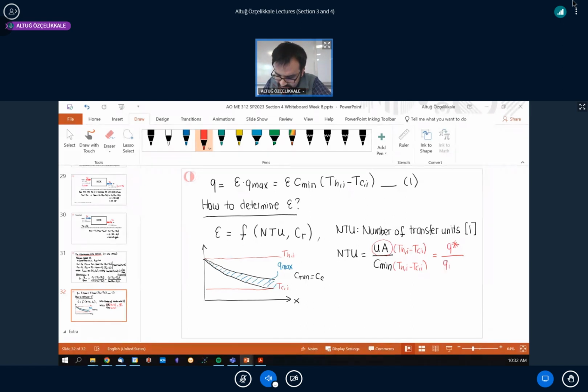That's not the actual heat transfer rate, but it's a measure of how effectively heat is being transferred across the interface. That's something like Qmax, I'm sorry, Q star. And this is multiplied by UA, where A is the actual area. And the maximum heat transfer is when the area goes to infinity, right? So that's the idea.